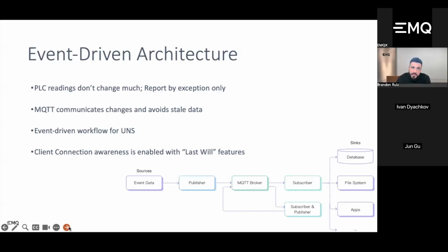So how do you work around that? Given the decoupling nature of MQTT as a whole, you can set up your system where it only reports by exception. What that means is instead of your robotic arm transmitting and processing a data point that says I'm applying 50 pounds of pressure every second, with that same data point repeating over and over again for weeks, days, months, you're now only going to transmit a data point when it goes from 50 pounds to 55, or 60, or even lower. Just a state change. That's the reporting by exception, and that will help you cut through those large cloud fees that you'll be seeing otherwise.